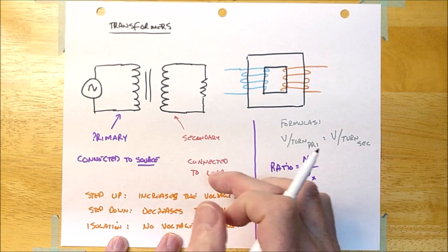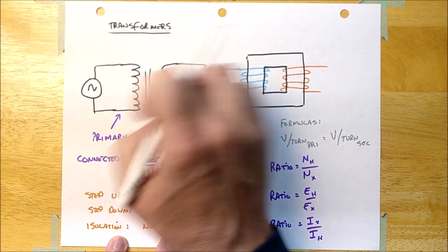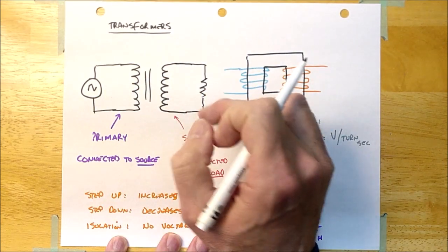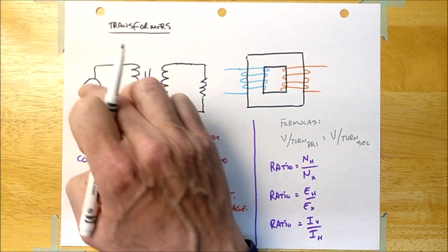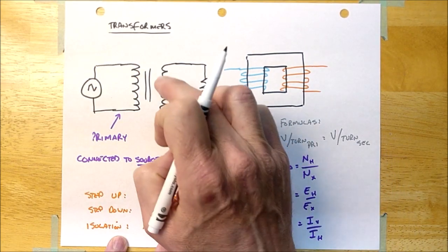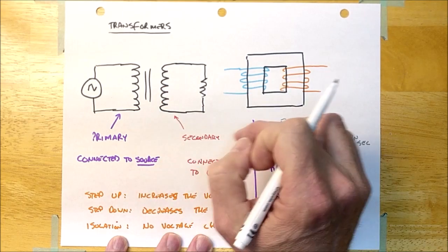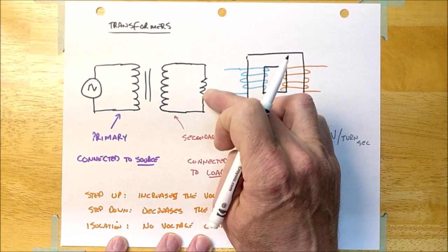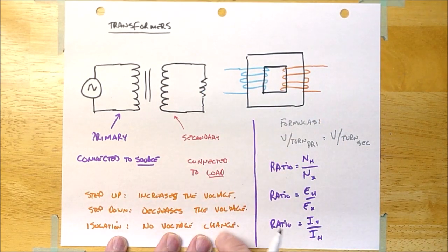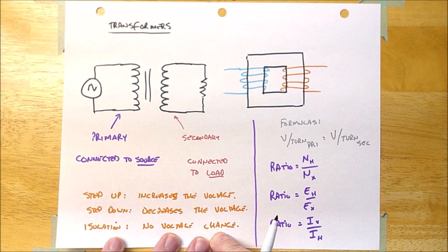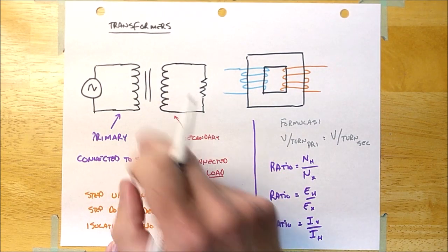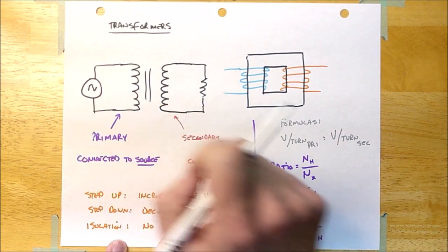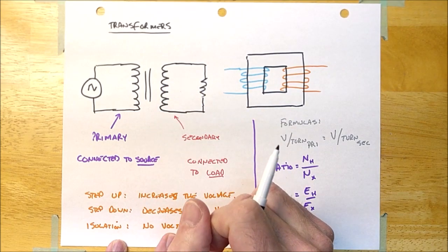And it doesn't matter if it's step up or step down. Even if it's a step-up transformer and you're going 240 to 600, the 240 volt, or the lower voltage, would be the primary because it's the one that's connected to the source. And the 600 volts would be the secondary because it's connected to the load. Okay, guys? There's another kind of transformer that you can experience, and that is what's known as an isolation transformer, and it just doesn't change the voltage at all. So an example of an isolation transformer is one that would be 120 volts here and 120 volts there.